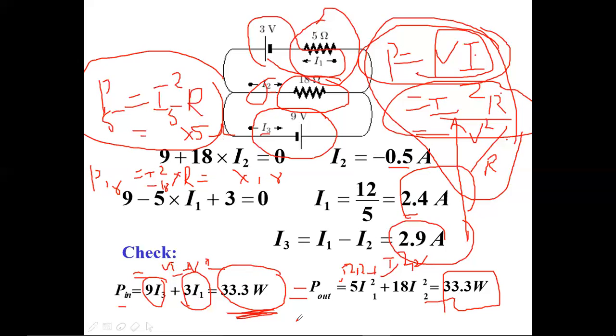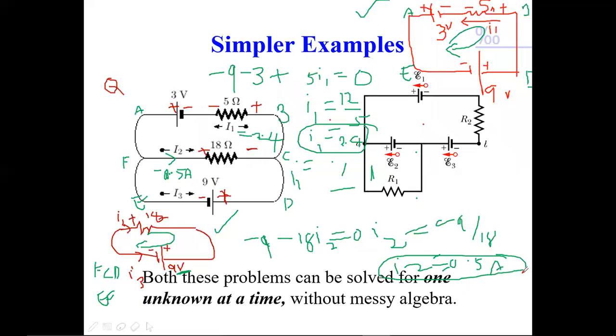The input power is going to be consumed in the output. So this is one of the different ways of approaching. Hope you understand what I'm trying to say. There is no fixed way of finding currents; naming of branches is not mandatory. You can follow the representative values and current directions already given in the problem. But the sign indication is very important, and the assumption of your loop, either clockwise or anti-clockwise, is important for writing these types of equations.